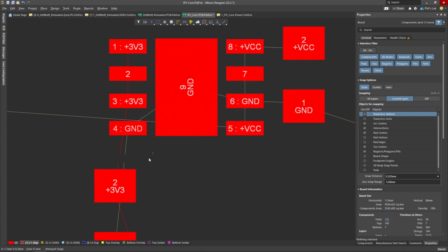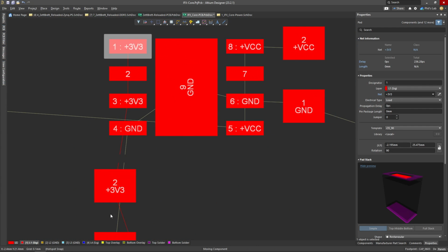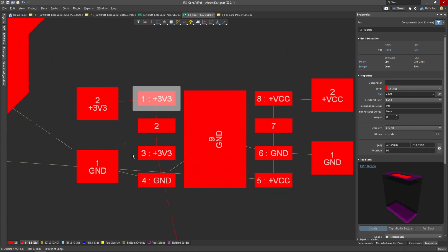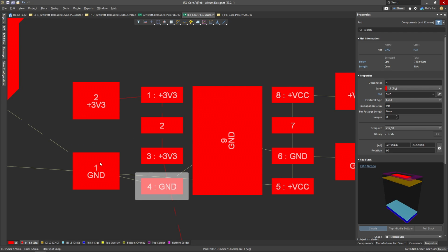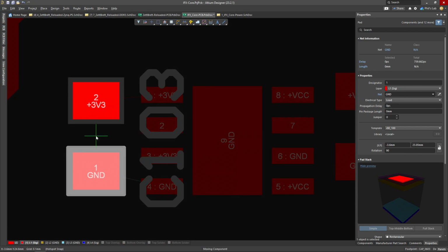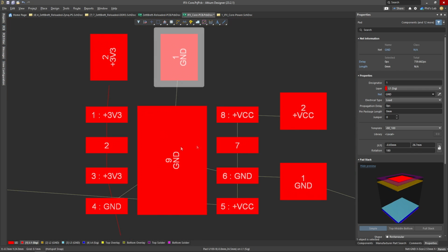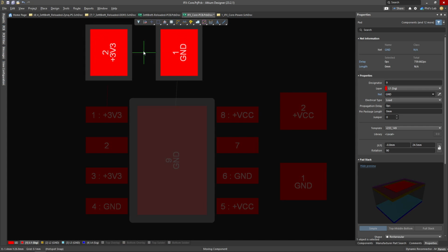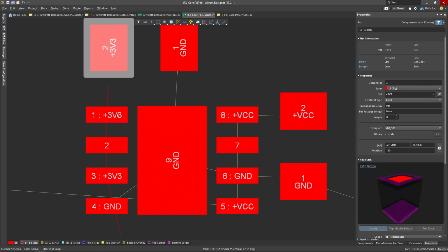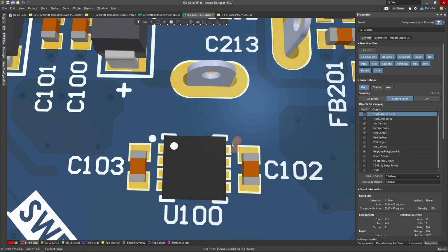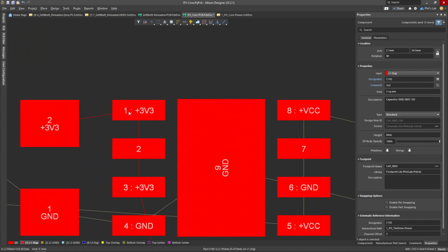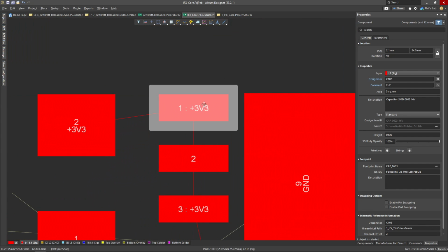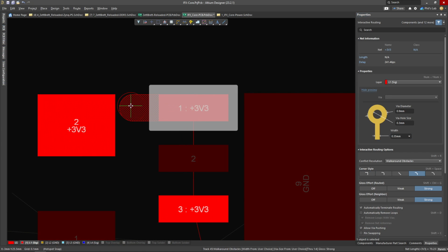Remember, on the output side, we have pad 1 or pin 1, and we take our output capacitor and make sure our loops are small, for example, pin 1 to pad of our capacitor and pin 4 to pad of this capacitor. Alternatively, depending on what loop might be better, and because we have this exposed pad, we could place the capacitor something like so. Again, short connections then and short loops. Let's then say we've placed our capacitances like so, symmetrically. Then what we do is take as wide a trace as possible from our pads to our pads. So in this case, about 0.35 millimeters is as wide as the pad.